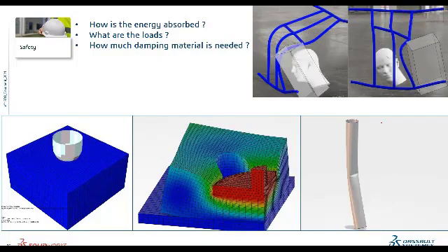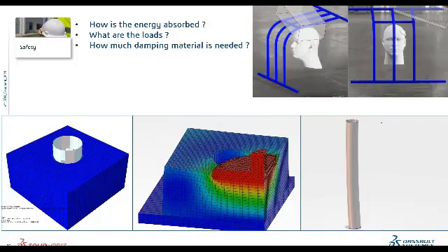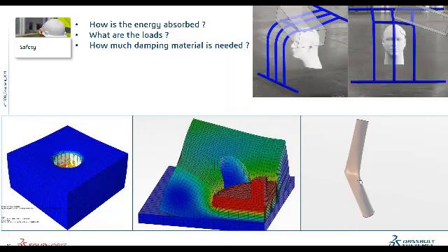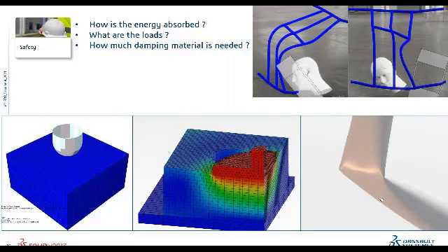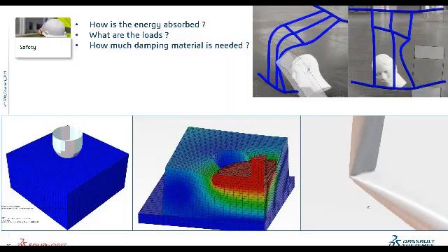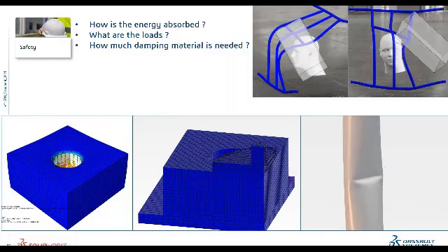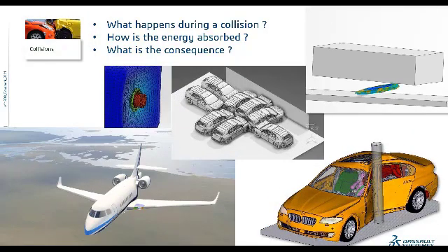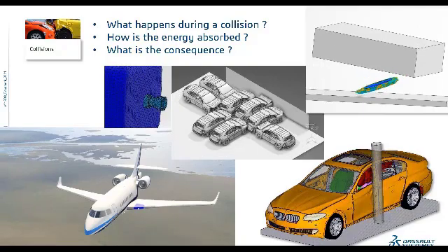So with respect to the hyperelastic materials, we will be able to perform the bending analysis of a pipe and different types of drop test phenomena, where we can make use of the mannequin and then understand what the contact patch is. So where is the impact point on a mannequin, or on a particular object. So different types of collision tests like crash test, bird strike analysis.